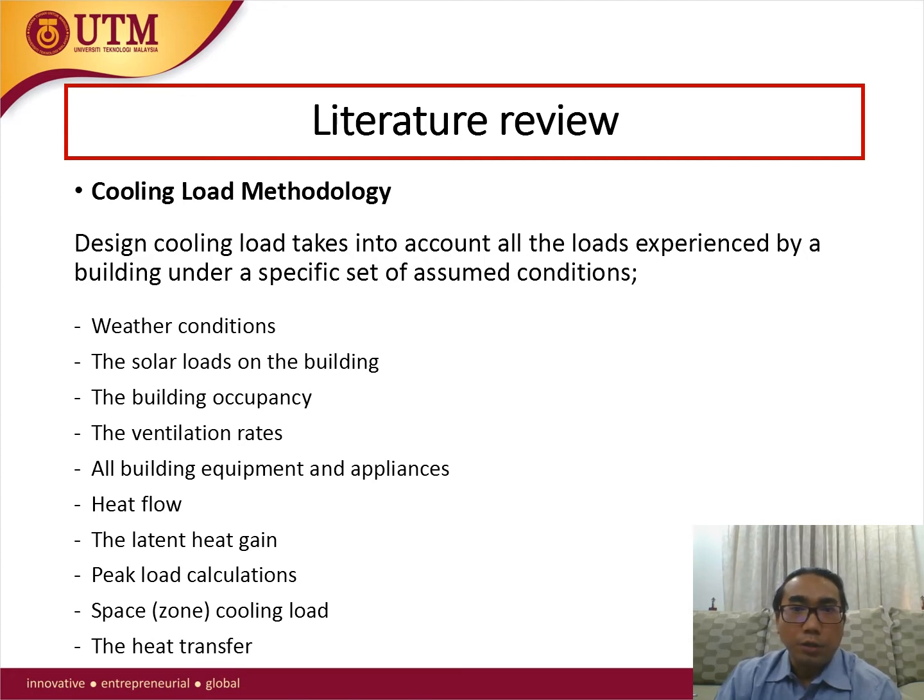The coil load is used to determine the size of the cooling coil and the refrigeration system. Space cooling load is a component of the cooling coil load. The heat transfer due to ventilation is not a load on the building but a load on the system.